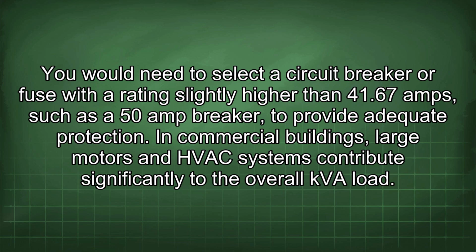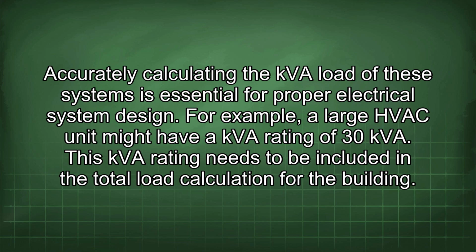In commercial buildings, large motors and HVAC systems contribute significantly to the overall kVA load. Accurately calculating the kVA load of these systems is essential for proper electrical system design. For example, a large HVAC unit might have a kVA rating of 30 kVA. This kVA rating needs to be included in the total load calculation for the building.